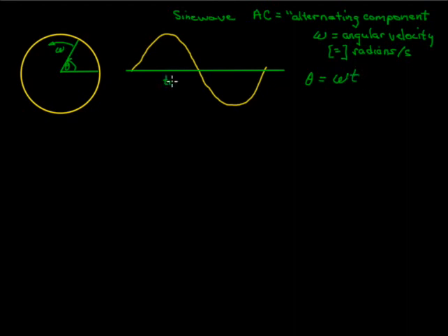The value of the sine wave changes with time. Its instantaneous value is equal to the y-coordinate of the vector as it moves around the unit circle. If this happens to be a current signal, then the instantaneous current is the y component of the vector as it moves around the unit circle. The period of the wave is the time that it takes the hand to move one revolution around the clock. It is also the distance on the time axis that the wave moves before it repeats itself. We typically report the period in seconds.